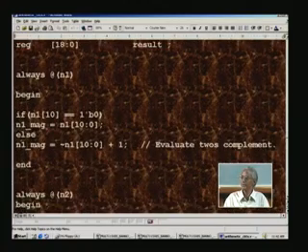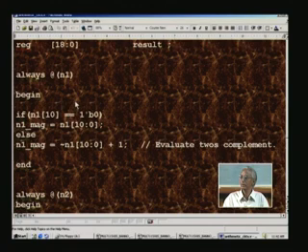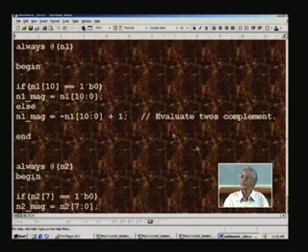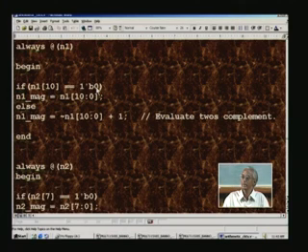What we are going to do, as mentioned before, is extract only the magnitude of the two numbers n1 and n2 in these two blocks. So whenever n1 changes from one value to another, only then we take this value. Now here, if n1 10, which happens to be the sign bit, is 0, that implies it is a positive number. So all we have to do is take n1 as such and call it n1 magnitude. This means the n1 number is in magnitude form. So is the case for n2 magnitude, which is basically the same here.